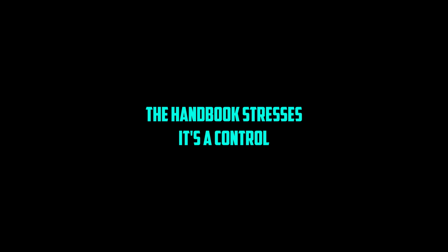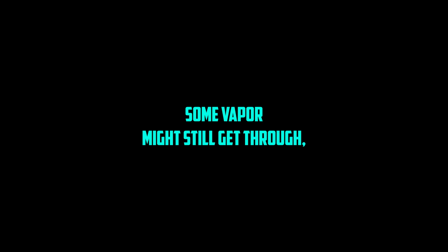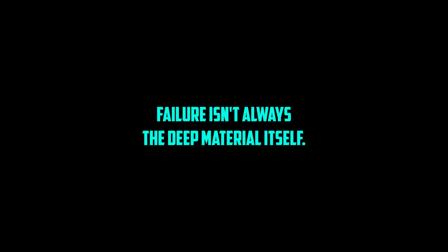What if you have rising damp already? Treating it. Chemical injection is common, drilling holes and injecting fluids that line or block the pores in the brickwork. The handbook stresses it's a control method, not always a complete cure. Some vapor might still get through. BS 6576 is the standard. Failure isn't always the DPC material itself. Often it gets bridged, like soil piled up outside or plaster inside going down past it.